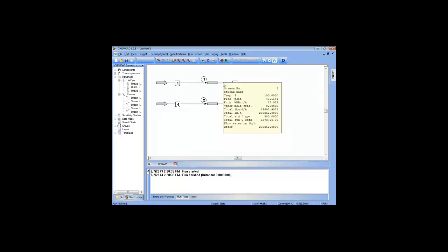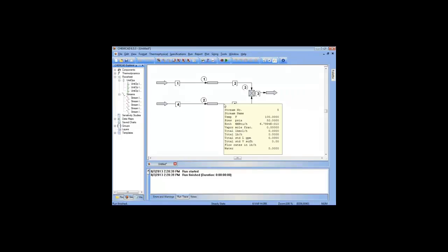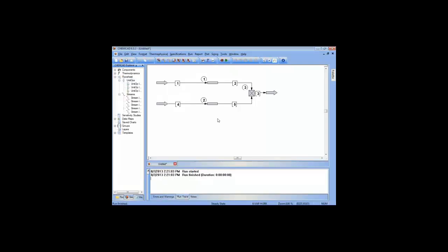Run all. See, this hasn't changed any. That's still 45.6 pounds pressure out through that pipe. This one's a shorter run, so you'd expect a little higher pressure, a little less pressure drop. Oops, something wrong here. Let's do that again. I guess I goofed when I put in the total flow of 500 gallons per minute. Okay, there we go. Like I said, we'd expect a little higher pressure out here, a little less pressure drop because it only has a 250-foot run of piping, and that's what we see.